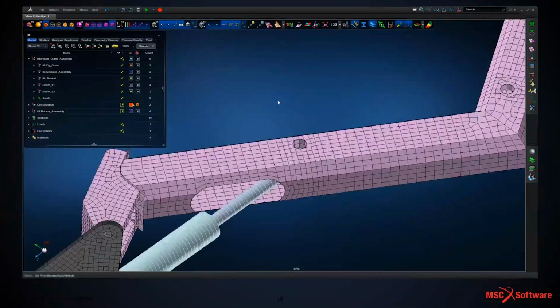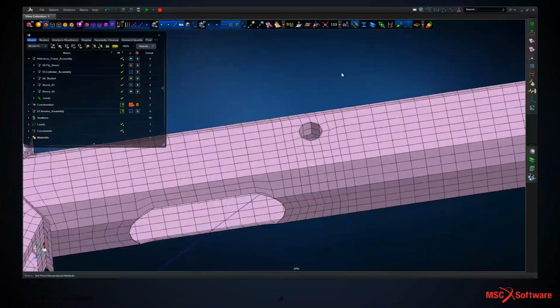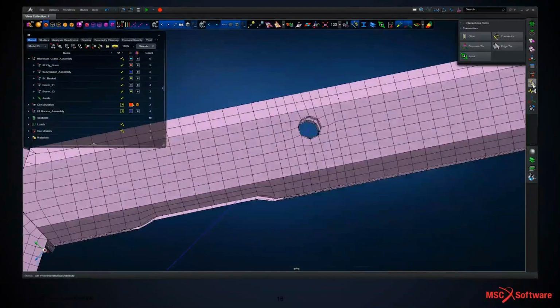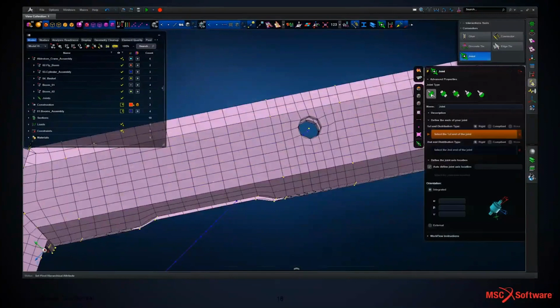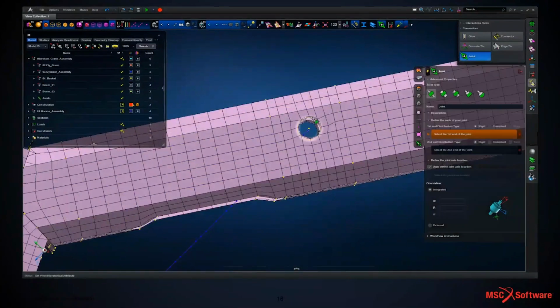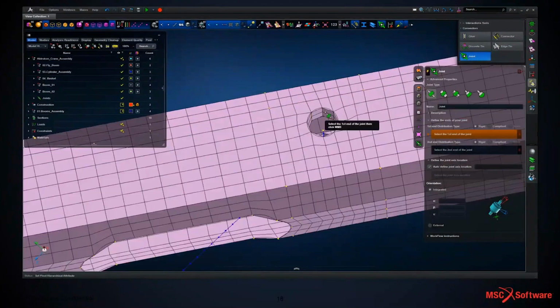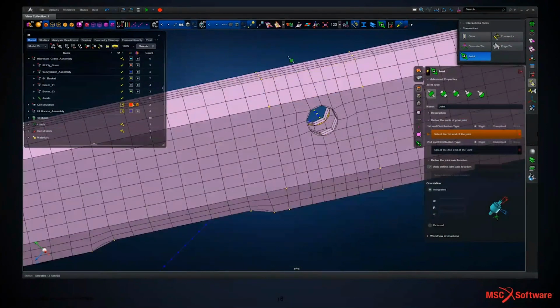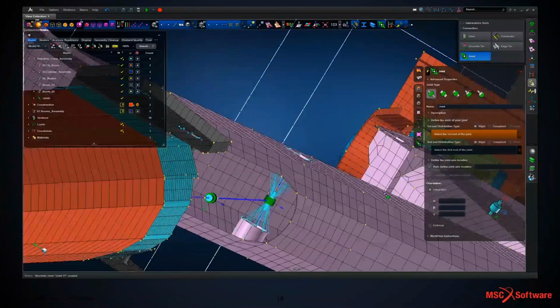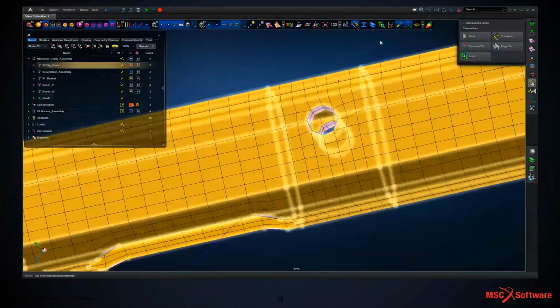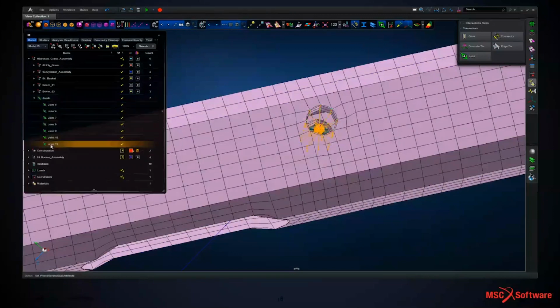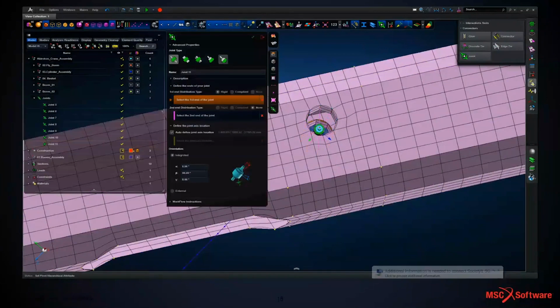So we've got this shell meshed strut and then a bar meshed secondary struts, and we're going to use a joint. So this is going to be a revolute joint. We've got lots of different types of joint within the model. So pick the surfaces of the mesh that we want the joint to be attached to, and then a central node or series of entities, and the joint is created, and the display markers show the orientation of that joint, and we can then view that joint in the tree and modify, change the joint type, anything like that, with no problem whatsoever.